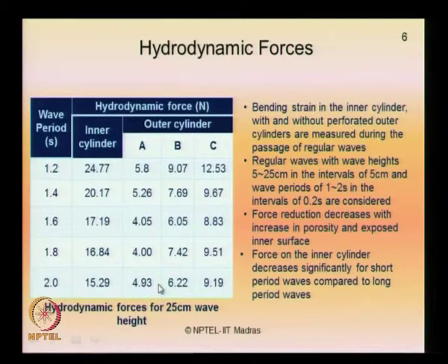It is seen that there is a force reduction, and this force reduction decreases with increase in porosity. You can see here that when the porosity increases, the force reduction decreases. Further, the forces on the inner cylinder decrease significantly for a short period wave compared to a long period wave. The reduction is significant for a short period wave compared to a long period wave.